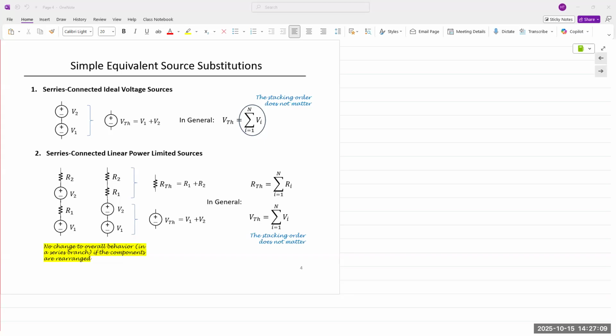And I'll explain why. If you wish to measure voltage, what do you do? Take our meter, take the two terminals of the meter, and connect to those two points. So if we have a circuit and we want to know what the Thevenin voltage is between any two points, you take a meter and measure the voltage. That's it. That's your Thevenin voltage.